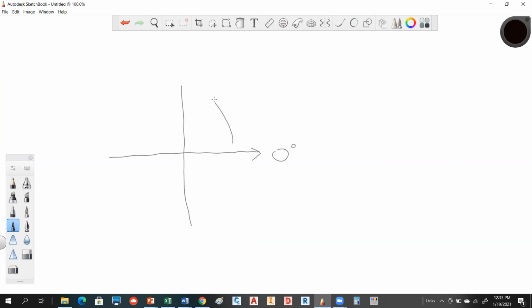If you go this way, that's a plus angle, and if you go this way, that's a negative angle. So what we're saying is we're looking uphill or we're looking downhill. This would be 90 degrees and this would be 90 degrees. So in a true vertical angle, 0 is looking straight ahead, and this is also called your horizon. And 90 minus and 90 plus, this is actually the vertical line.